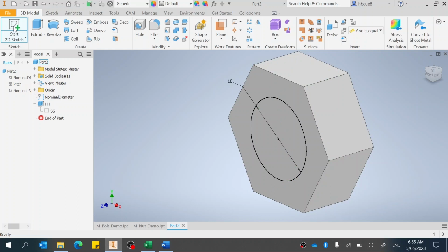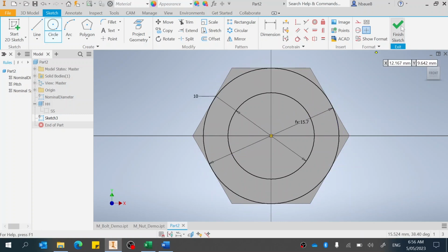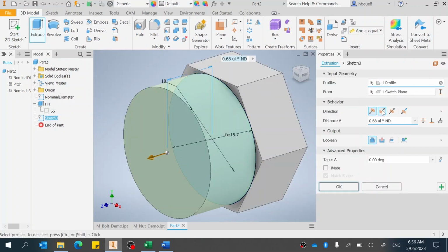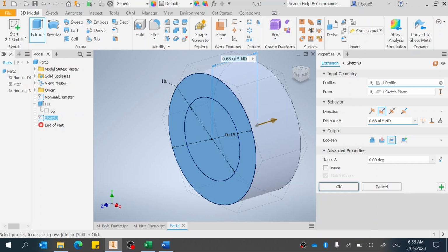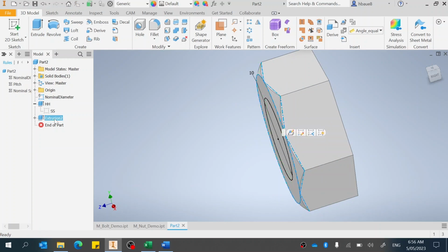Now we'll put a chamfer on the bottom of this head by creating a circle that has a diameter of spanner size, and we'll do an extrude of that circle, take it backwards at an intersection of 55 degrees. And just chop off those corners. You can label that one the bottom chamfer,